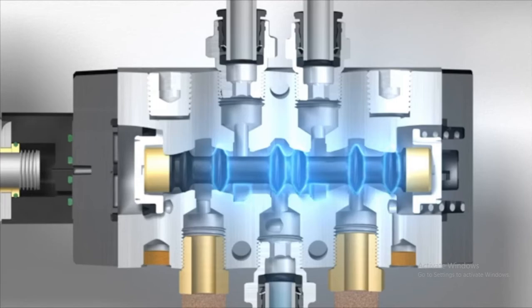In this position, you can see that this land blocks air from going out the number 4 working port, and instead is forced to go out working port number 2, because the grooved lower section of the spool allows air to flow past it and out to the number 2 working port. In order to change the direction of the air to the number 4 working port, the valve needs to be